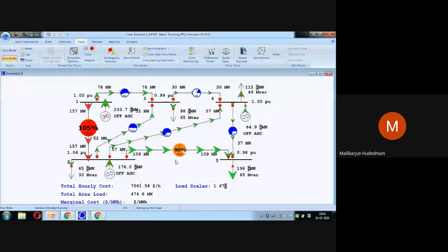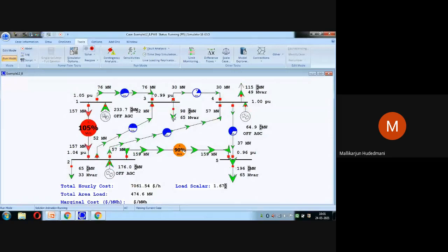Now you will find tremendous pressure from this generator on the transmission line, injecting power to the grid. There is a path for the delivery of power. You might ask me, why is this line getting burdened? Why not this one? My friends, this is how the distribution of power in the system takes place. It will be the shortest path, the low impedance path, for the delivery of load. So for loads to be delivered at the extreme right, extreme left, and down, the best available path is chosen automatically.